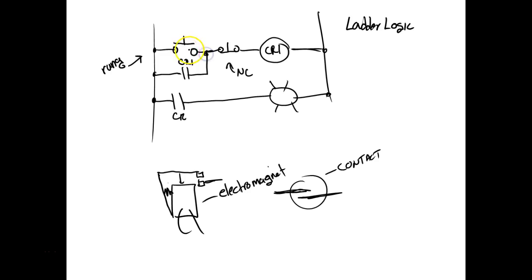So right now I come over here and press the button, energize the CR. It's a momentary contact, but when it energizes it, what does it do? It closes that contact right there. And the light comes on, which is going to close this contact right here, and the light's on. And it seals itself in, right? So now we bypass the start button, and now how do I stop this thing? Well, I come up here and press that button, it would open up the circuit.